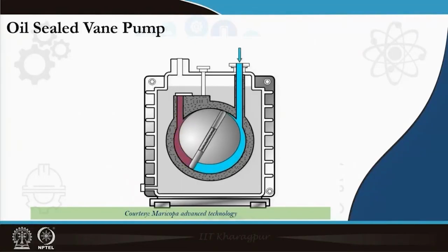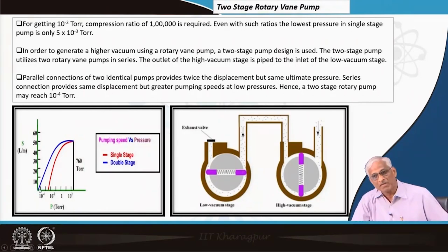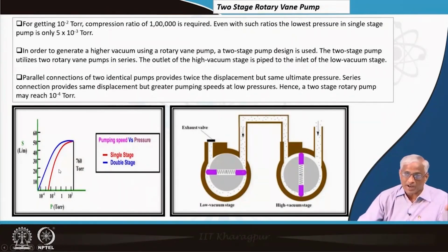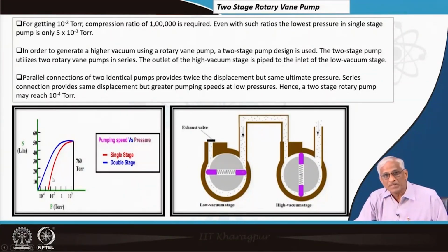Okay. So, you try to design various aspects in vacuum pumps to put various levels of vacuum or various levels of pumping speed. With all these things, if you look at the left side, pumping speed falls as a function of pressure. At some pressure, it reaches ultimate. If you put 2 stages, it will be better vacuum. So, exhaust is either connected to another pump or it is directly exhausted to atmosphere. Depending on that, pumping speed variations are there.